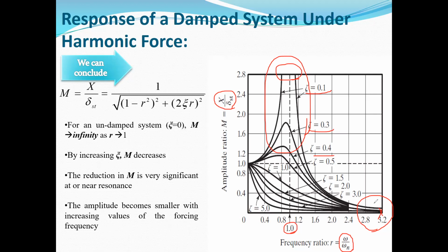If you consider that the amplitude remains the same, I mean remains 10 Newton, and the amplitude of the response is, for example, 2 millimeters, by increasing the omega with the same value of the amplitude of the excitation, you can see that the amplitude of the response will decrease significantly, and sometimes by increasing omega you can go to 0. I mean, you can see that the response will go to 0 despite the amplitude of the force remaining the same.